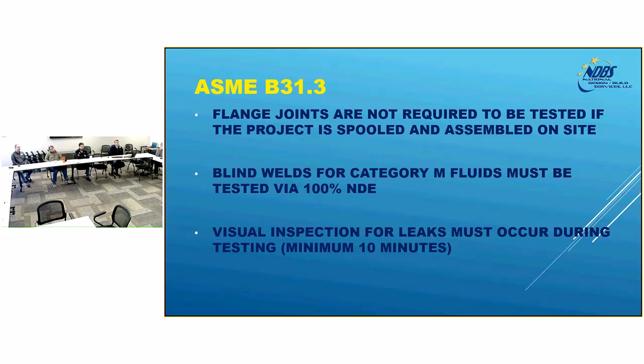A lot of times leak testing will go on for 30 minutes, 2 hours. I had an owner who wanted leak testing done overnight. The code only requires 10 minutes. So you can remind your owners of that.